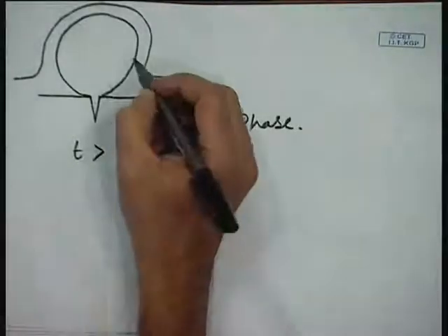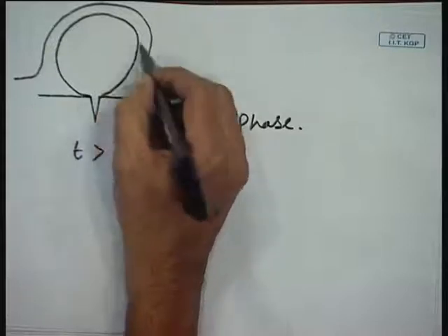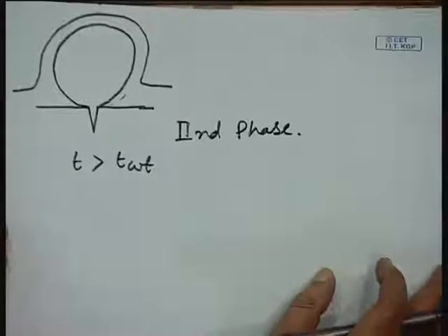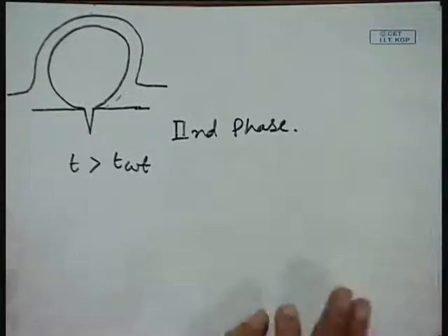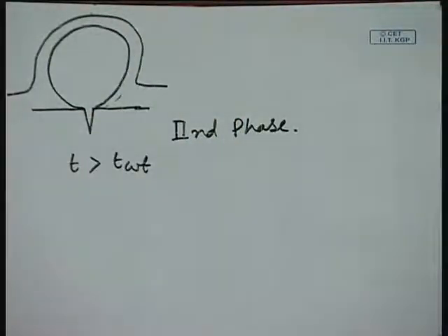Already, the temperature in the vicinity of this bubble is higher than the saturation temperature, but it is not very high. So, as that is not very high, the heat transfer has now become slower. Evaporation has also become slower. So, now this bubble growth is not inertia controlled, it is heat transfer controlled.